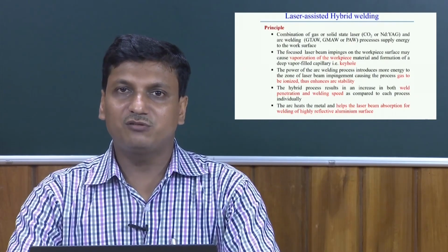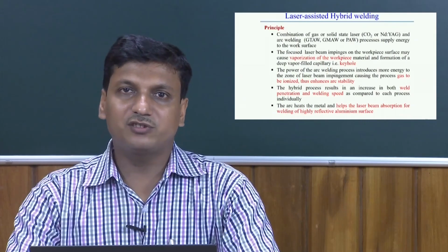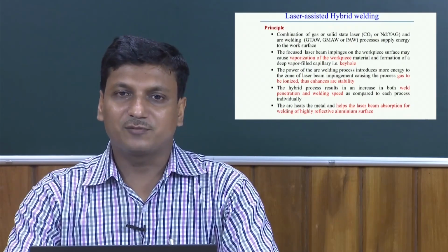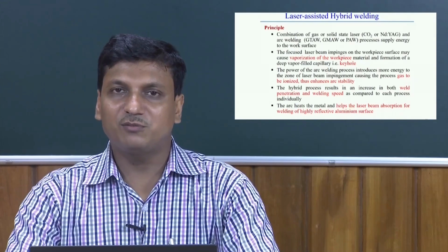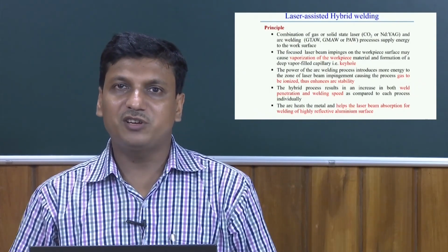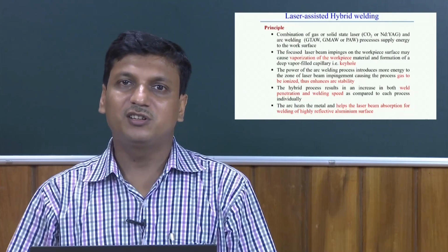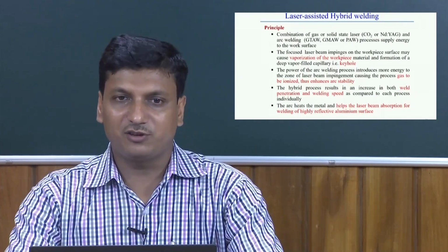That means, as compared to individual laser welding processes or any arc welding processes, it is advantageous in both ways, in terms of creating a high depth of penetration, and we can probably use a relatively higher welding speed that may have limitations in individual processes.